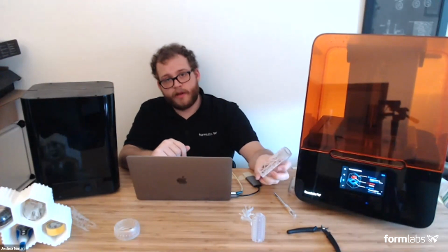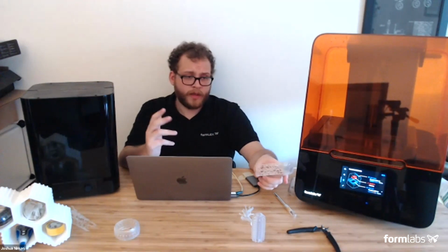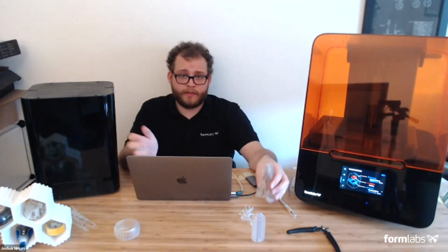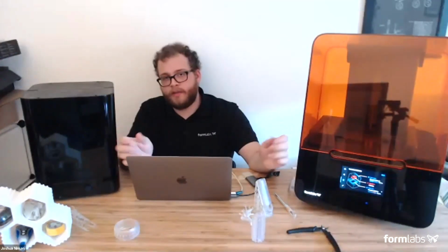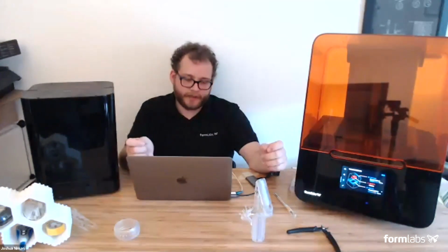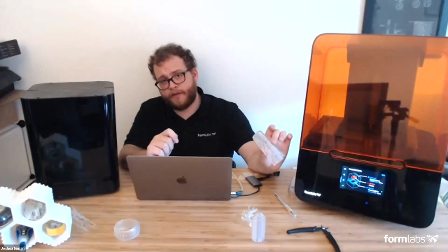The thing you have to consider there is that adding pigment will always scatter light, will diffuse light. It will make it cure differently. You might not get exactly the properties. So if you can add just a little bit to get a tinge, you'll have much better success. You can also dye it after the fact.